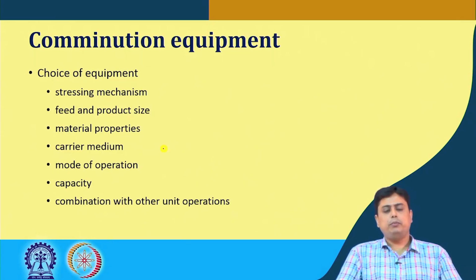So, basically the choice of equipment depends on several criteria. One of the most important is the stressing mechanism, the kind of particle that you are trying to achieve, because such kinds of particles will come from different stressing mechanisms, or a combination of stressing mechanisms that would lead to several ranges of products. So, we will see in the overview of these equipments how they use which of the stressing mechanisms.